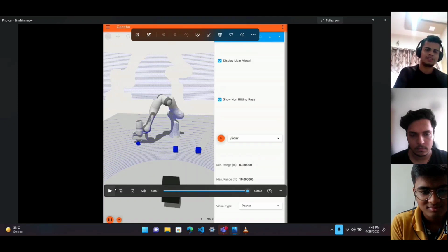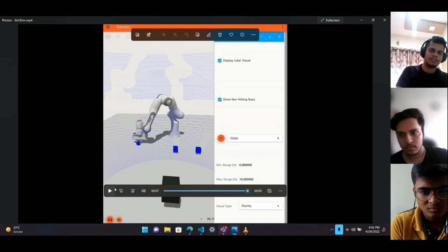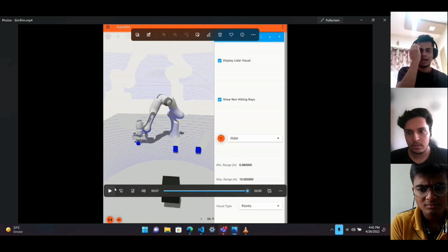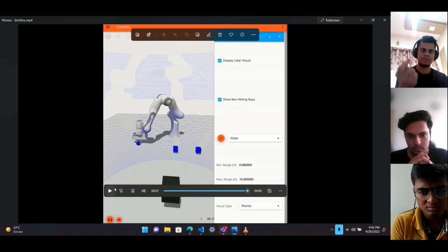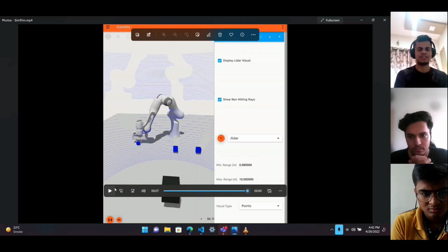We can observe that the lidar is operating in real time and is sending 3D points to our software at 60 frames per second. And every 60 frames, we calculate the locations at which these objects are present in the simulation, and then we feed it to the MoveIt framework so that the gripper moves to that object location. After the gripper holds the object, we send the target location, the place location, to the MoveIt framework so that the robot performs the pick and place operation.